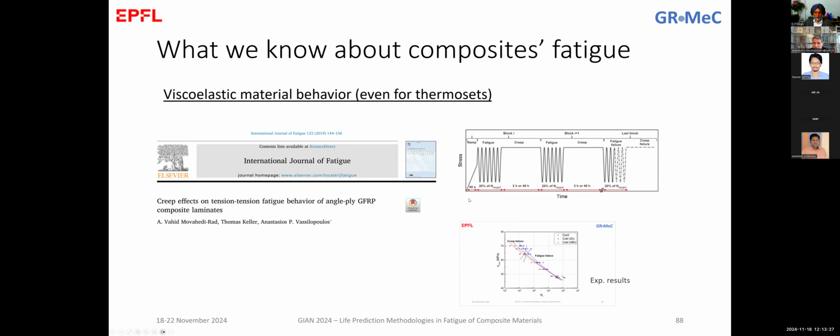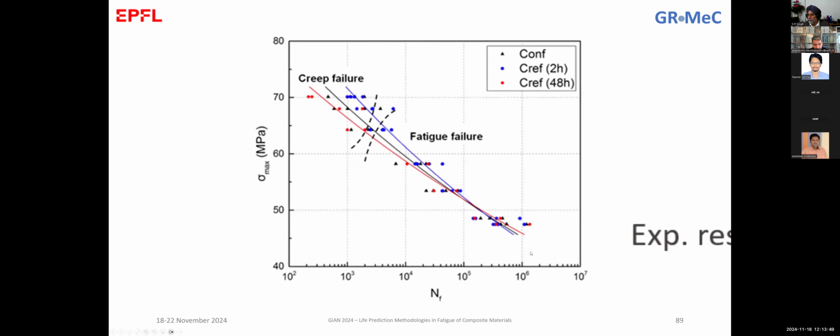We've seen also the other way around, again, the effect of the viscoelastic behavior of the material by doing the same test, but now instead of letting the material recover, we were creeping the material. We were keeping the material at the highest, so the sigma max, the maximum cyclic stress, for a certain lifetime. And there, of course, we were continuing this up to the end.